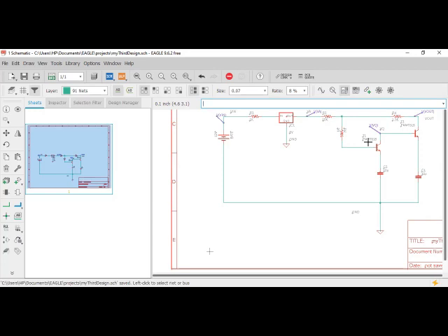The first time you design your circuits using the SPICE components, make sure you have the SPICE ground node, which is this. It's very important for simulations. Then you label, you add values, you rename. If you need to, you rename the component you are using.